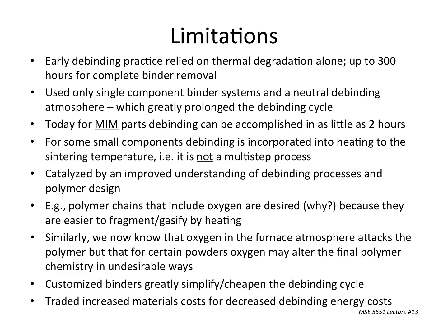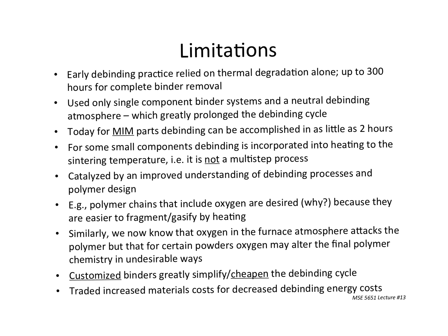All right, so early binder practice. Related to thermal degradation alone, as you've heard already, you could have up to 300 hours for a complete binder removal, and longer than that if the parts are big and thick and fat. It's very complicated because with something thick, you have not just one environment, you have a variety of environments inside that thick piece, and that complicates and slows everything down.